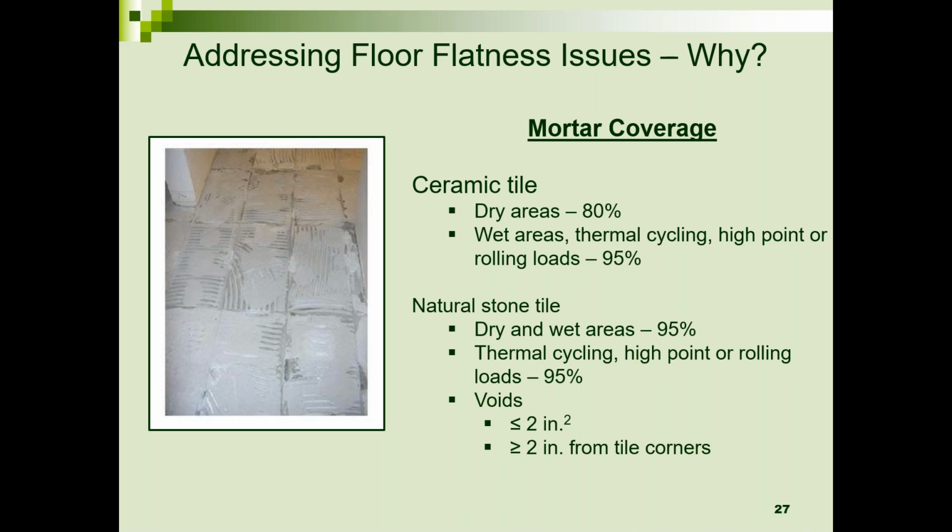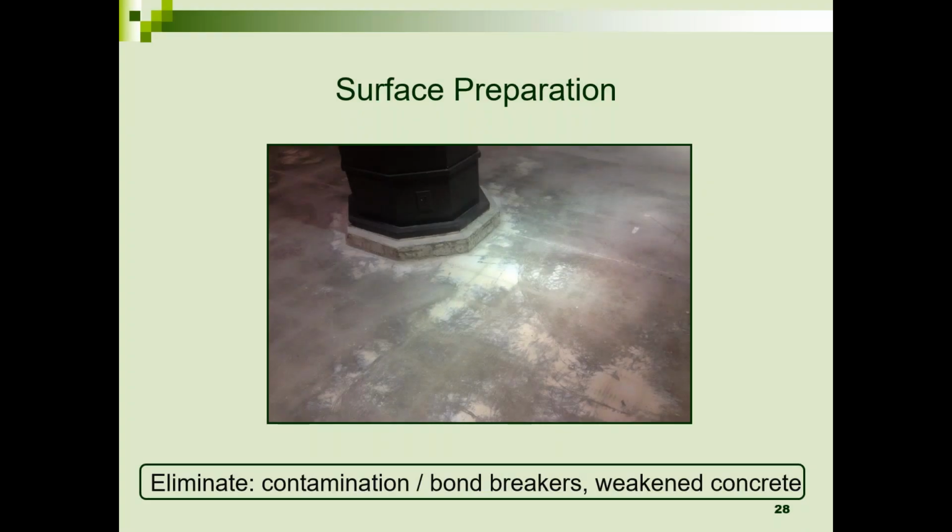And also a comment to the specifiers, you never specify mortar thickness. You specify mortar coverage, 80%, 95%, and it's up to the contractor to figure out what size trowel to use, and what will help him figure that out. The setting material manufacturer generally will supply recommendations for size of the trowel, meaning the notches. So again, correct mortar coverage is greatly enhanced or ensured if you have flattened that floor first, meaning 1/8 inch in 10 feet for large format tiles, 24 inches or greater.